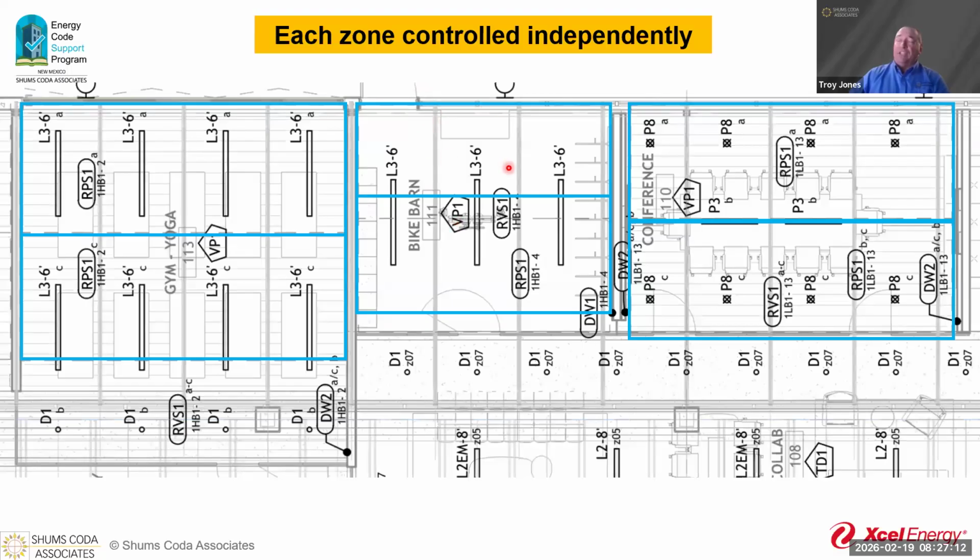But we still have to maintain our daylighting controls here as well. So when those lights come back on, that's going to be initiated by the occupant sensor. Then our daylighting controls are going to take over and say, hey, the sun's coming through here. We're getting suntans at our desk. We need to turn these lights down. That's the sequence of controls that we need to have.